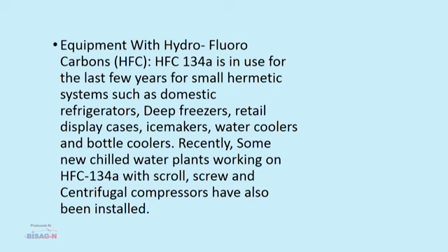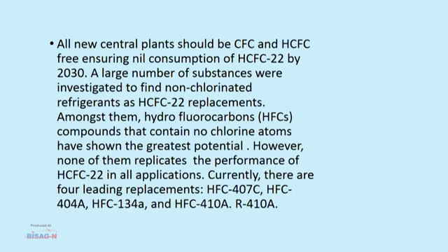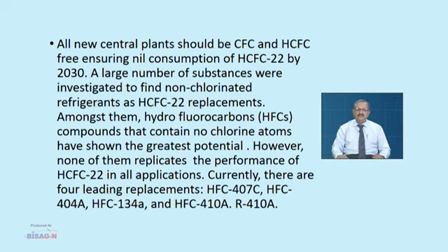Equipment with HFC, hydrofluorocarbons. HFC 134A is in use for the last few years for small hermetic systems such as domestic refrigerators, deep freezers, retail display cases, ice makers, water coolers and bottle coolers. Recently, some new chiller water plants working on HFC 134A with scroll, screw and centrifugal compressors have also been installed. All new central plant AC should be CFC and HCFC free, ensuring nil consumption of HCFC 22 by 2030.